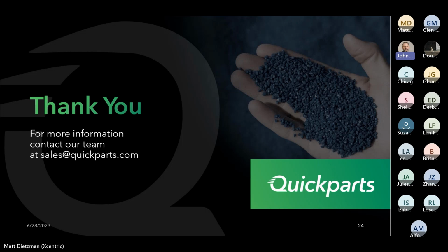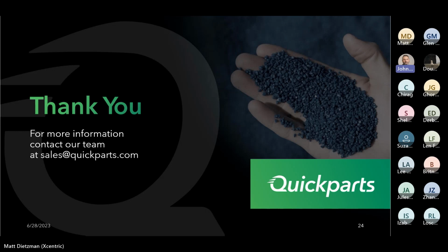Next one, what's the best way for me to try out different materials with the same design? In the past, what we have done with some customers is, if you're within the family, like ABS or like a nylon unfilled, your shrink rates are going to be very similar, typically within 10%. But if you're looking to go across families like ABSs and nylons, what we've done in the past is take an average shrink rate. And the customers, depending on the dimensionals, try to make it work.